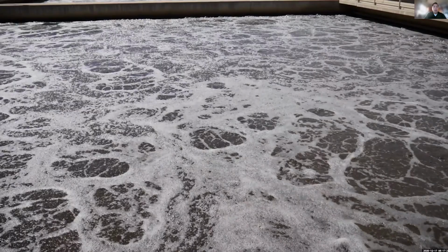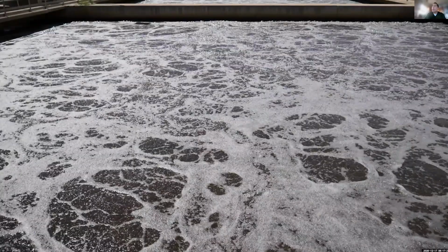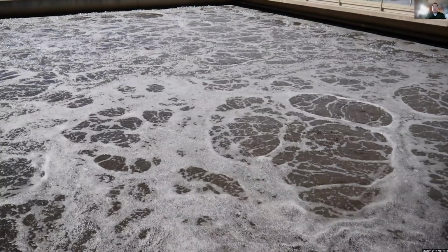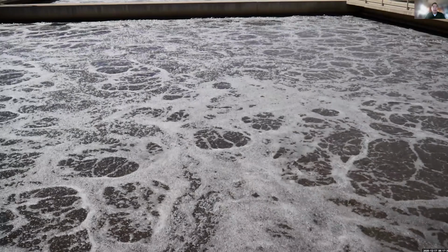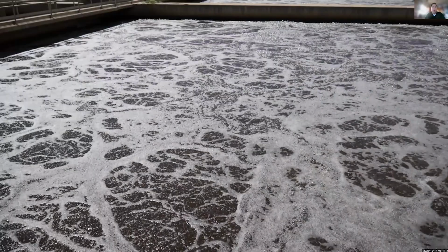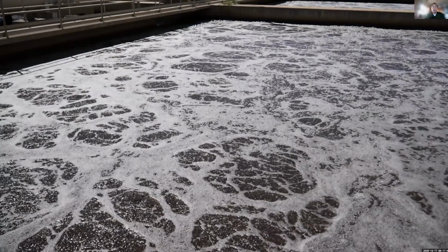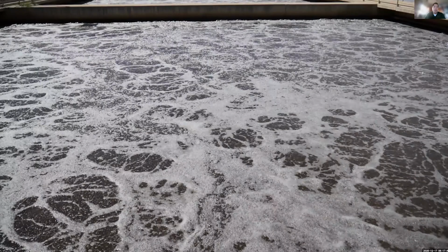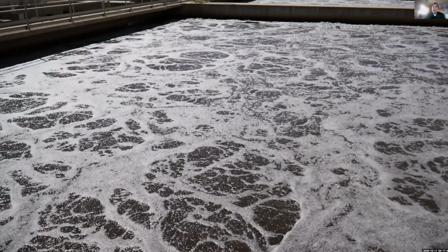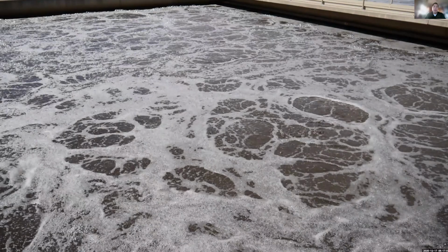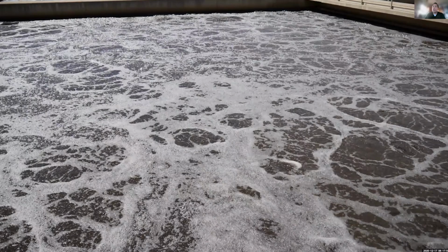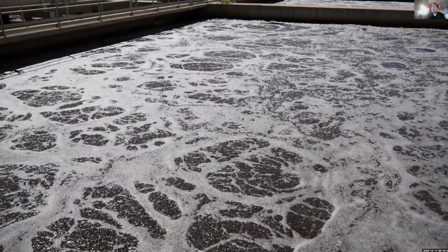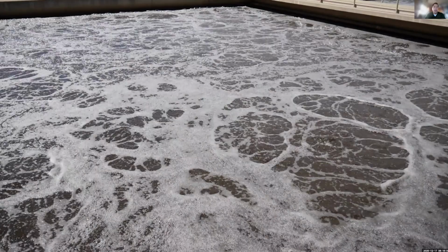So this is what a wastewater facility that's running correctly, that activated sludge would look like, if it's healthy and it's processing wastewater correctly, it's treating organics. This would probably be removing ammonia efficiently. As you can see, like I said, it has that dark brown color, lots of little tiny white bubbles. So that indicates that your dissolved oxygen is being delivered correctly. And then you don't see large bubbling anywhere that indicates any line breaks.